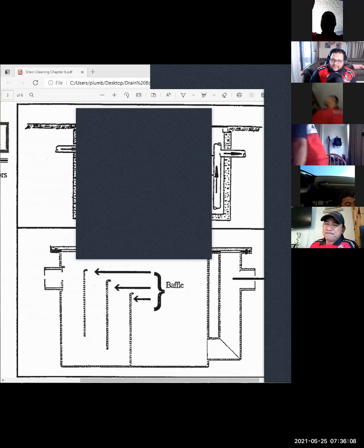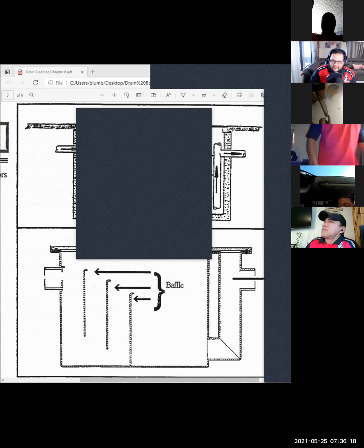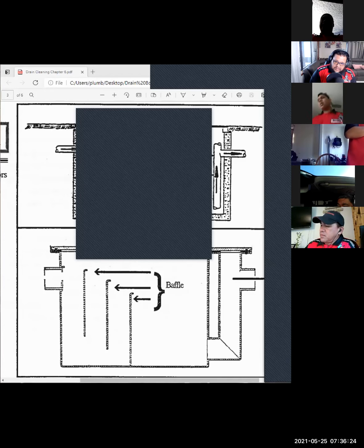So let's do simple math, which I'm not going to expect anybody to do the calculation here. We got grease traps anywhere from 250 gallons, 100 gallons, but our maximum capacity is 1,500 gallons on Maui, 2,000 gallons on Oahu. Does anybody have an idea of what the discharge is on a commercial dishwasher, average? Just throw a number out there. Dump 5 gallons? Yeah, if you said 5 gallons, you'd be heavy. If you said 10 gallons, you'd be, I don't care if you say 20.